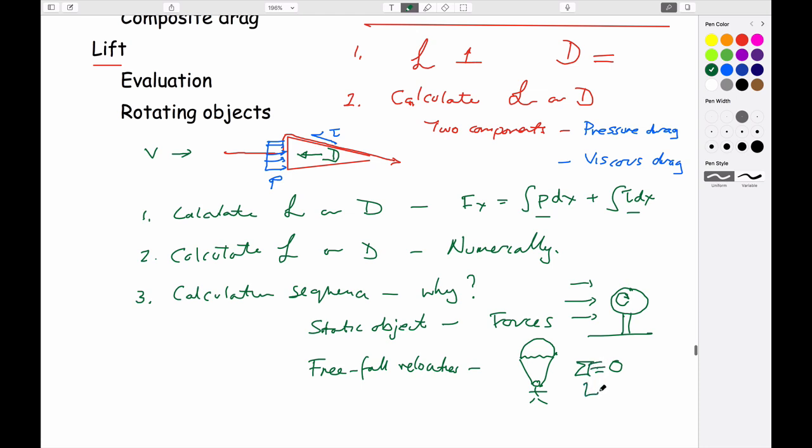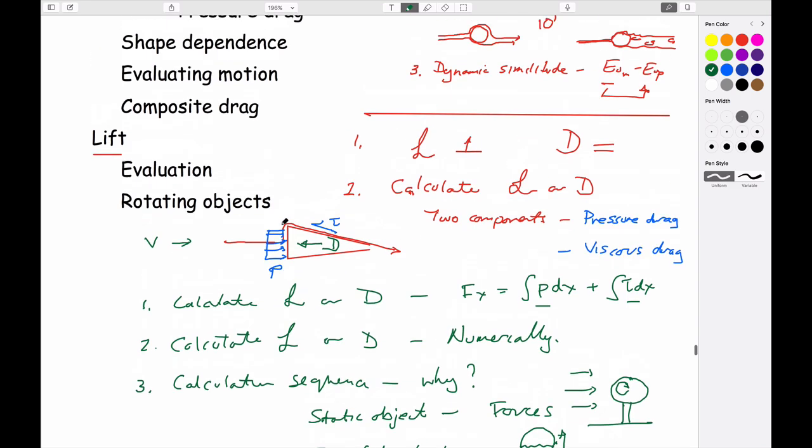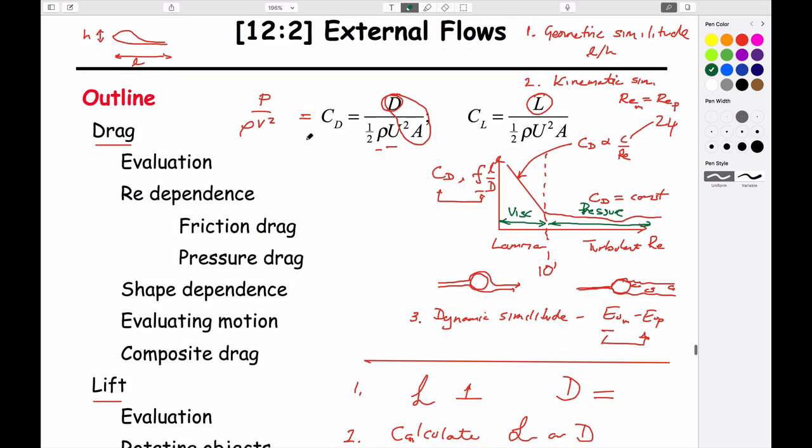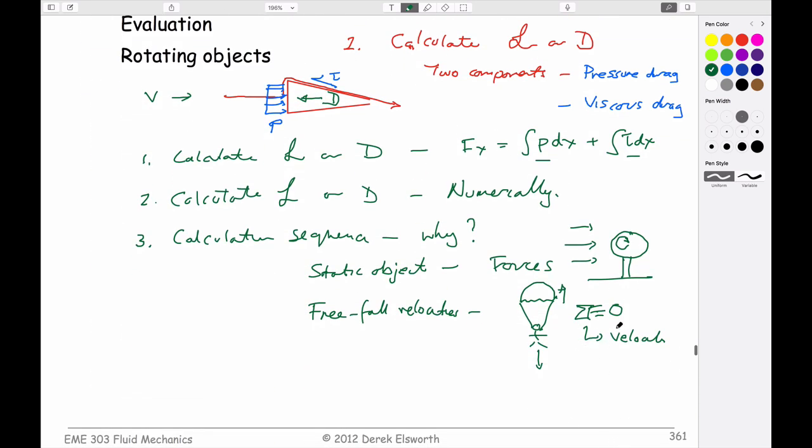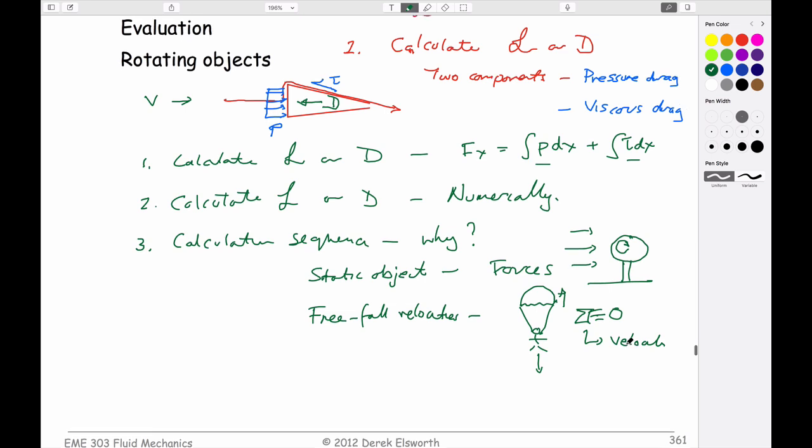And if you do this, then you can calculate the velocity. So you know that there's a weight acting downwards, there's a drag force acting upwards. If you equate those, and you can define those in terms of a coefficient of drag or a force that's applied, by just rearranging this, then it shouldn't come as any surprise that we can calculate from this the terminal velocity as you come down with the parachute or as you free fall in space. So those are the things you do, yeah.